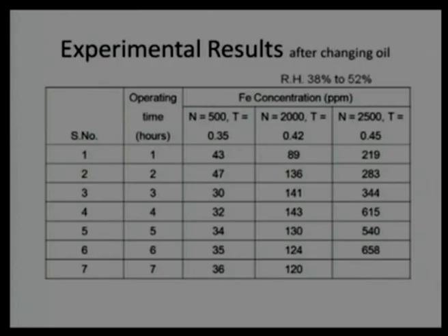Now, I can think in a different way. When the speed is increasing, the vibration level is increasing and the load level is almost 0. So, additional vibration phenomena is happening, and that is going to increase the fatigue failure, or the fatigue wear is going to increase with increase in speed. To confirm that, we applied a load, so that the vibration amplitude can be reduced. Even at high speed, it should not vibrate that much.